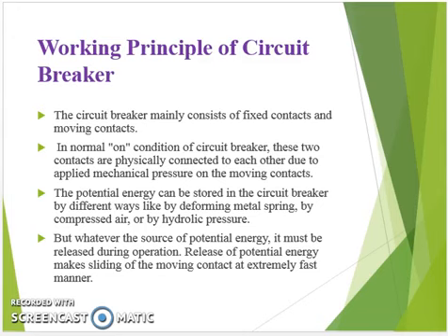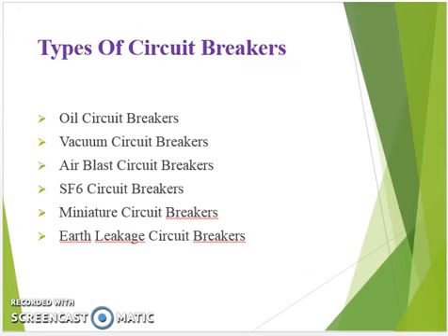So the types of circuit breakers will be oil circuit breakers. The arc quenching medium will be oil, and all the phases of the interrupters, all the contacts will be immersed in oil, and the oil tank will be grounded.